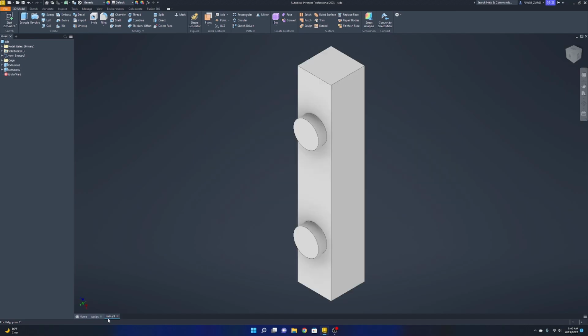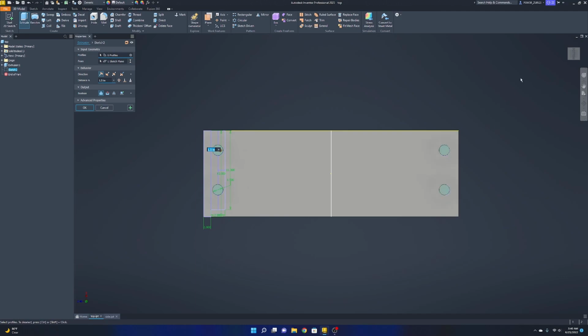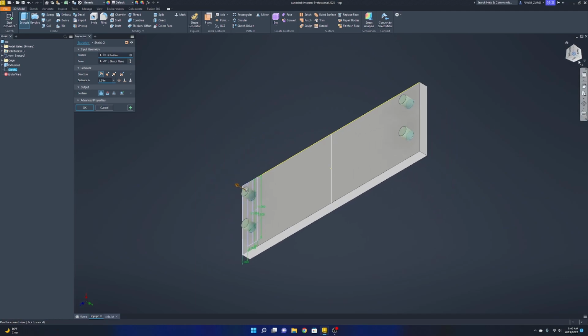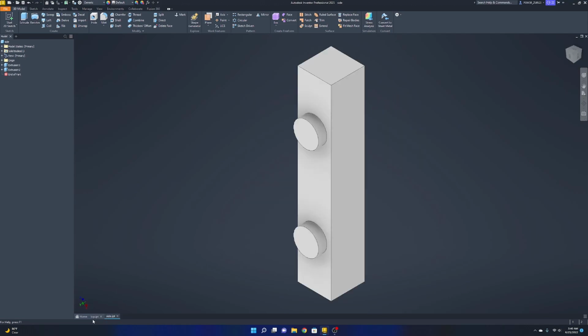And then I'll hit Save, Control S. And then these, I'm actually going to select all of these. And instead of being extruded, I'm going to go the other way, I'm going to go 0.5 in, and it's red now, and it's actually going to dig into those. All right, I'll hit save and save. Awesome.